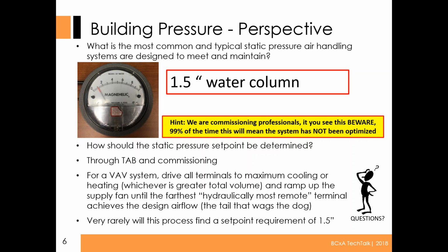I use water column here. Another reference, I'm using a few different metrics here. This is talking about the air handler. First of all, what is the static pressure that we typically refer to? What does the air handler run at? A lot of times you're going to hear this magical 1.5 inches is the static the air handler runs at, which is actually not static.